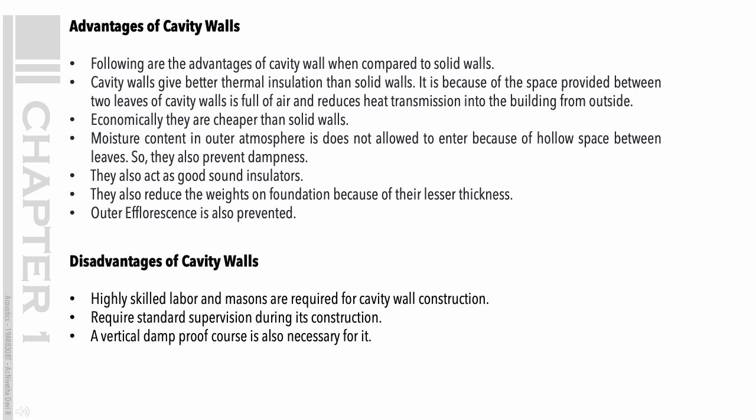Advantages of cavity walls. Following are the advantages of cavity wall when compared to solid walls. Cavity walls give better thermal insulation than solid walls. It is because the space provided between two leaves of cavity walls is full of air and reduces heat transmission into the building from outside. Economically they are cheaper than solid walls. Moisture content in the outer atmosphere is not allowed to enter because of the hollow space between leaves. So, they also prevent dampness.